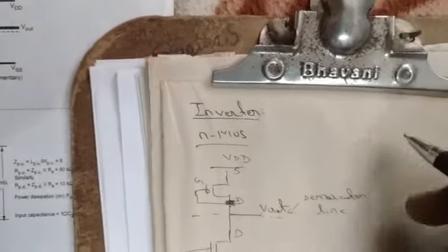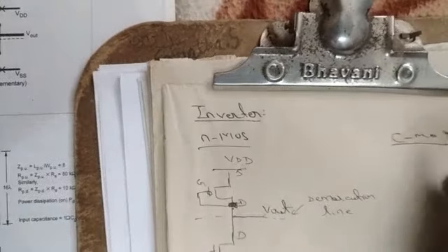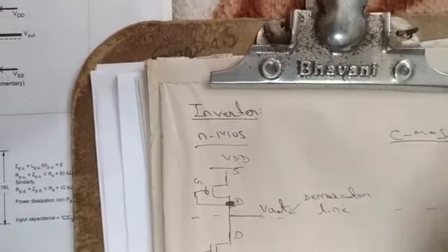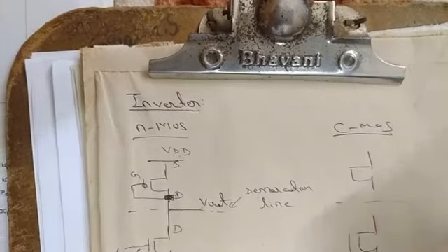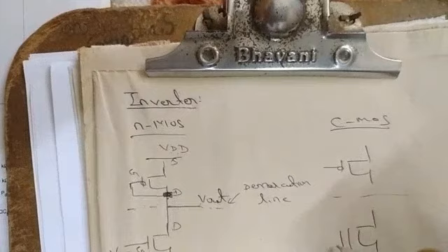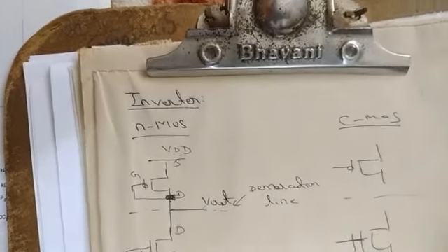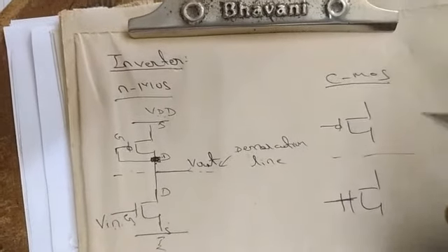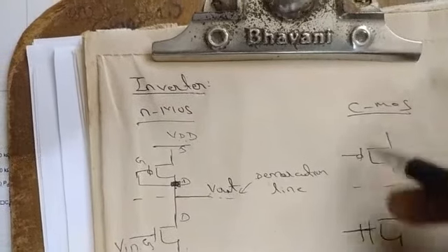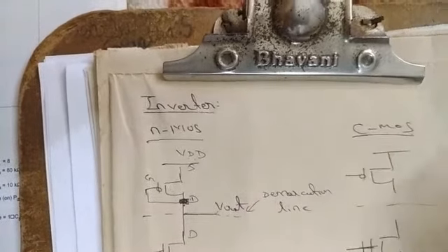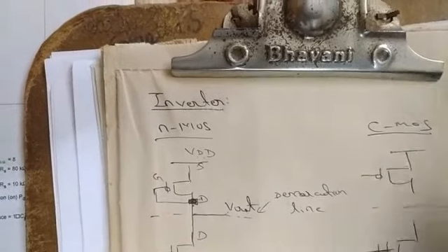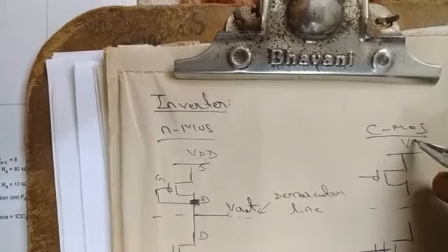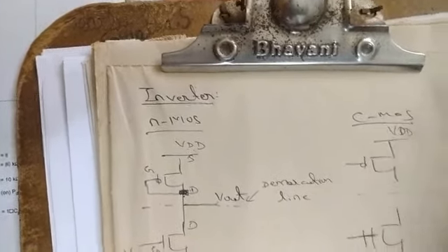In the same fashion, in CMOS, what will happen? The same thing. First the demarcation line. Next one PFET, one NFET, and people already know the connections for this, since it is just roughly drawn. Always the PFET should be placed above and the NFET below. The source of the PFET is connected with VDD.